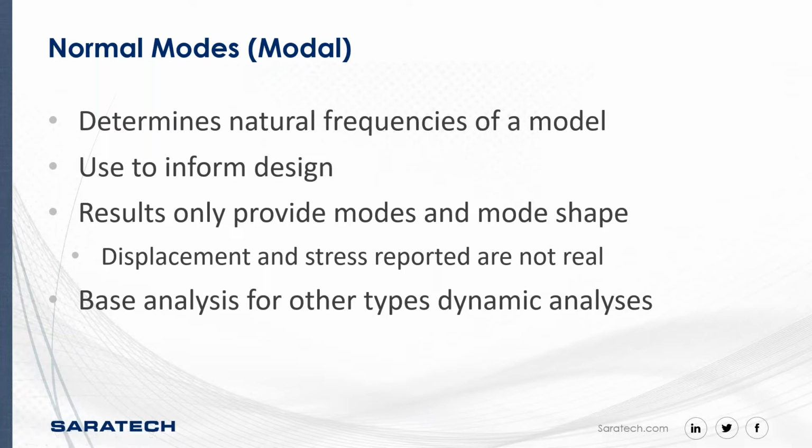Normal modes, for example, are also referred to as a modal analysis, and will determine the natural frequencies of a model. You can basically use this to inform your design, but keep in mind that a modal analysis will provide displacement and stress results, and these results are not real results, they're normalized results. So the modes and the mode shape are the most important things that we can get out of a modal analysis.